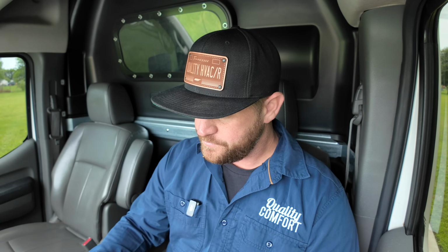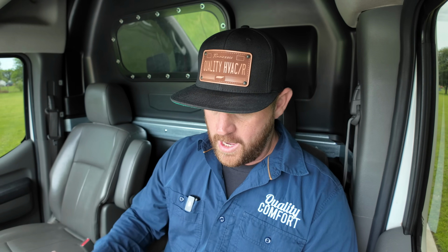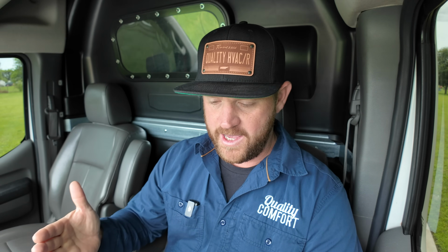So what I did, first of all, obviously, I went through and measured the space. I talked to the homeowner and then got some information from the insulation contractor and got the R values for the ceiling and for the walls. On this one, they're going to be doing glass, 3 glass garage doors. So I got all the R value for those garage doors because you need all that information to do a load calculation.